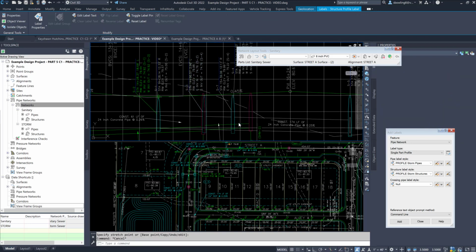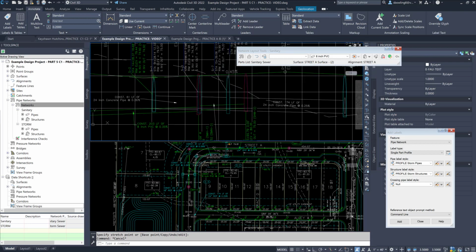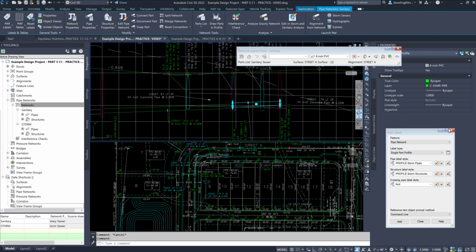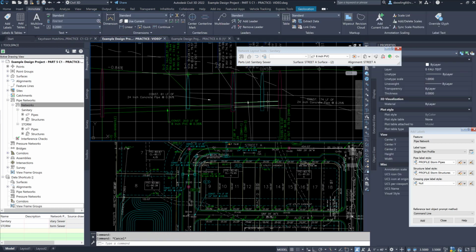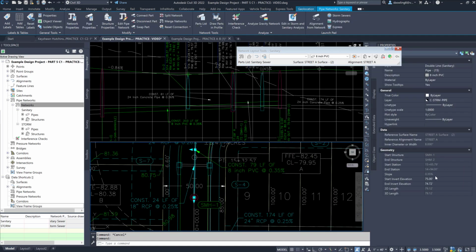Okay. So you can see that I'm in conflict here too, because you've got 75, 52. So what I'm going to do is I need to drop this at least a foot below the bottom of this. So I'm going to move this out of the way. You can actually drag these down like that. I don't recommend doing that though, just FYI. So what I'm going to do is just drop everything by 1.5 feet. So I'm going to take this, instead of starting at 75, I'm going to drop it a foot and see if that works. So 74, so that changes to 73.